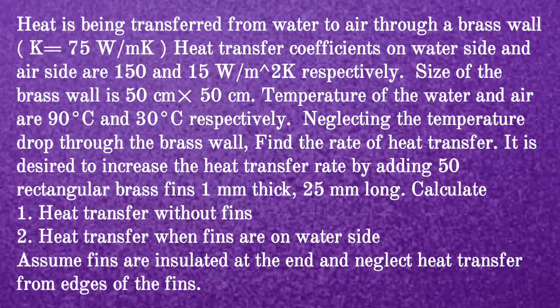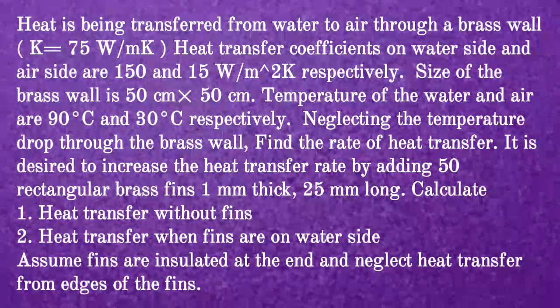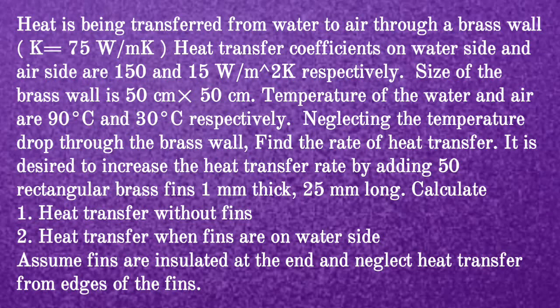It is desired to increase the heat transfer rate by adding 50 rectangular brass fins, 1 mm thick, 25 mm long. Calculate first the heat transfer without fins, second the heat transfer when fins are on the water side. Assume that fins are insulated at the end and neglect the heat transfer from the edges of the fins.